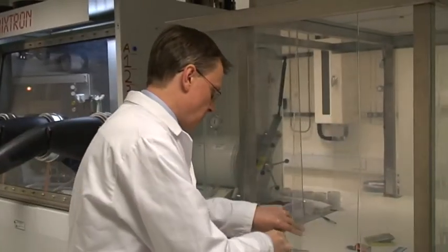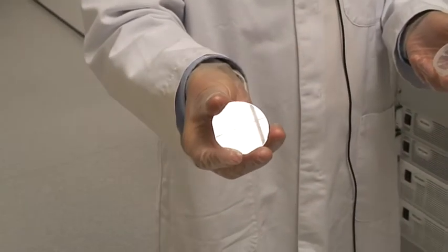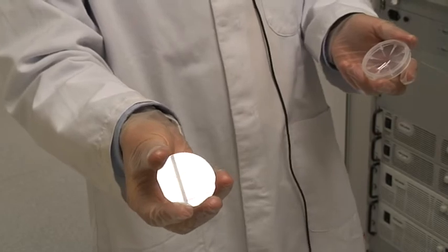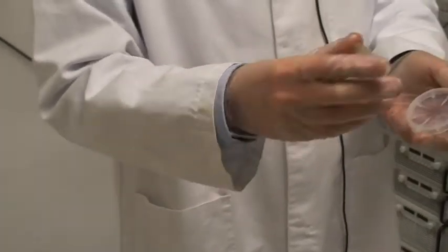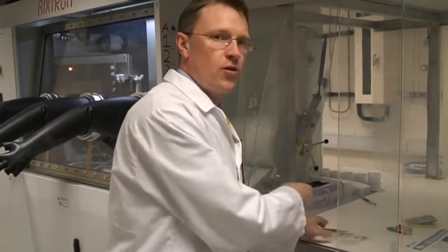These are actually very, very small, as this reactor is designed for very high uniformity. When we grow indium containing materials, there's some absorption, and you can actually see there's a yellow tint to the layer due to the high indium content. This is a sample which would emit green light if we were to shine a laser upon it. The applications of gallium nitride are mainly twofold.